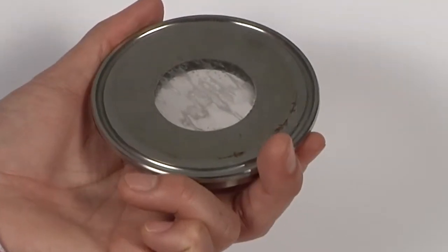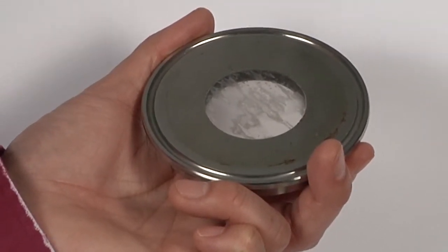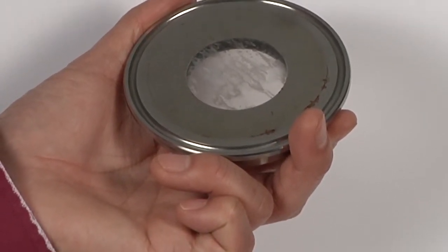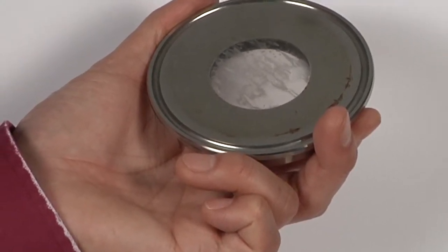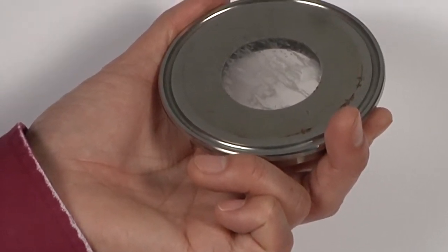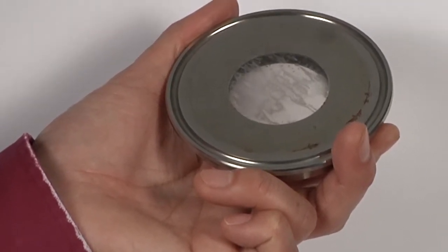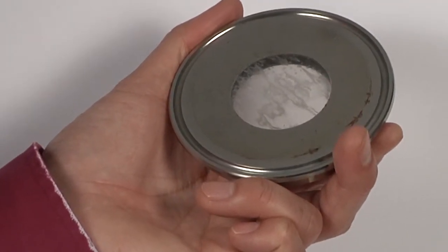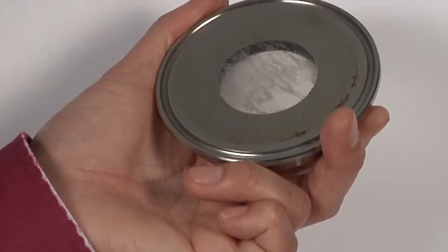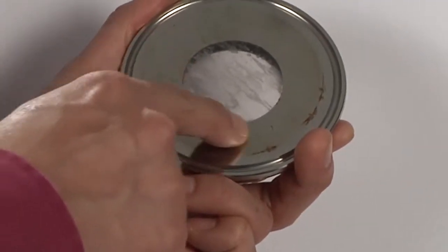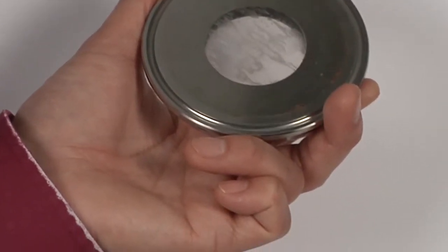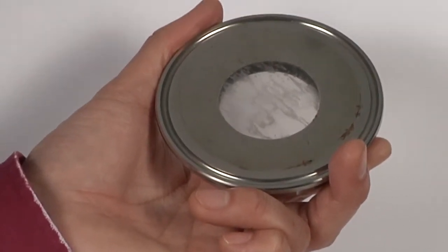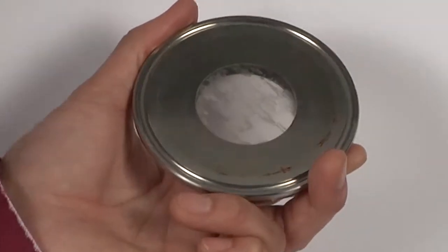Okay? This is another one of our products. This is a fused glass piece which is mechanically stronger than other types of side windows. But the glass here is still the same borosilicate glass as in the previous piece. Being surrounded by stainless steel doesn't make the silicon and oxygen in the glass behave in any different way. In fact, in a chemical corrosion scenario, this type of side window would start losing glass much more quickly. Right along the periphery of glass, there is a region of static tensile stress, and the glass will suffer accelerated corrosion right along this periphery where that static tensile stress is.